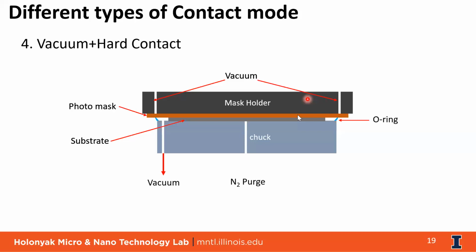And the second way, if we can afford more samples, instead of spin coating the exact sample size, you can increase your sample size. For example, if your process needs a 10 mm by 10 mm sample, you can spin coat something like 15 mm by 15 mm. After your spin coating and baking, you can just scribe off the outside region so that you get only the uniform spin coat region in the middle. These are the two options you have, because in spin coating you cannot avoid edge beads on the smallest sample. So that is impossible. The only way is after spin coating, either you remove them with solvent or you can scribe some of the wafer off to get a uniform coat.